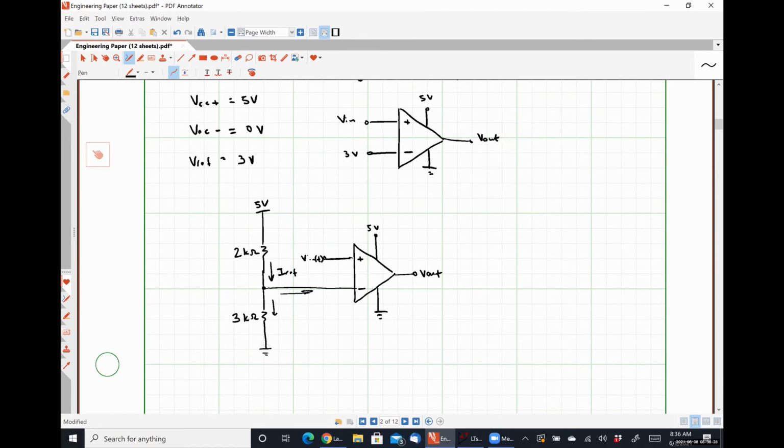Another thing that we would have to pay attention to, right now we're taking our output voltage to be an open circuit voltage, but it's actually very important if we were going to load this guy. So if we were going to measure our output voltage as the voltage drop over a loading resistor RL, which is pretty standard operating procedure, we have to pay attention to the size of that resistor as well.